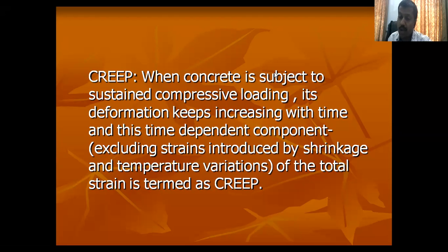Always remember now. Okay, why do we use concrete reinforcement in construction? First and important role: to improve the tensile strength of the concrete. Second is providing stability and all that. These are further applications. Whatever the concrete is, it is strong in compression.